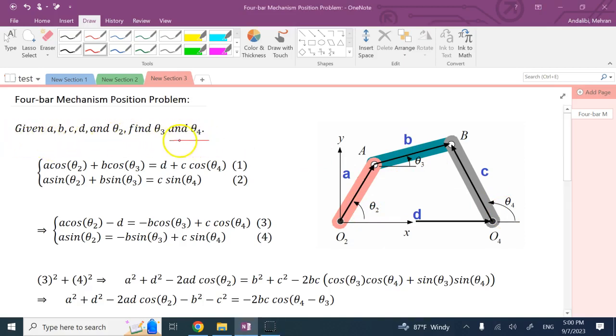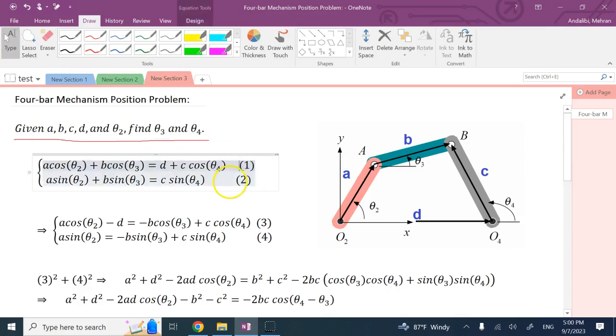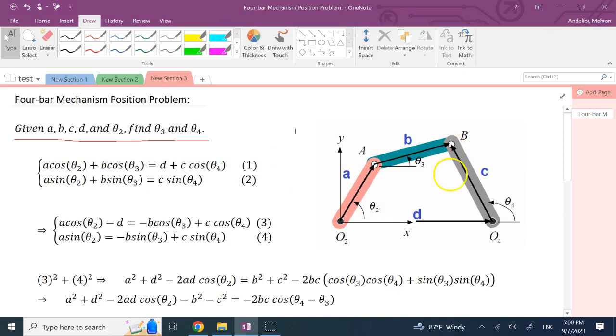So that is the problem. And what I want is an analytical solution, not a numerical solution, because if we move forward with our equations, look, what we do is basically we add the delta x's and delta y's that each member brings in, and you see these members form a loop, right? So we can say that the sum of the total delta x and delta y starting from O2, going through the loop and coming back is 0.